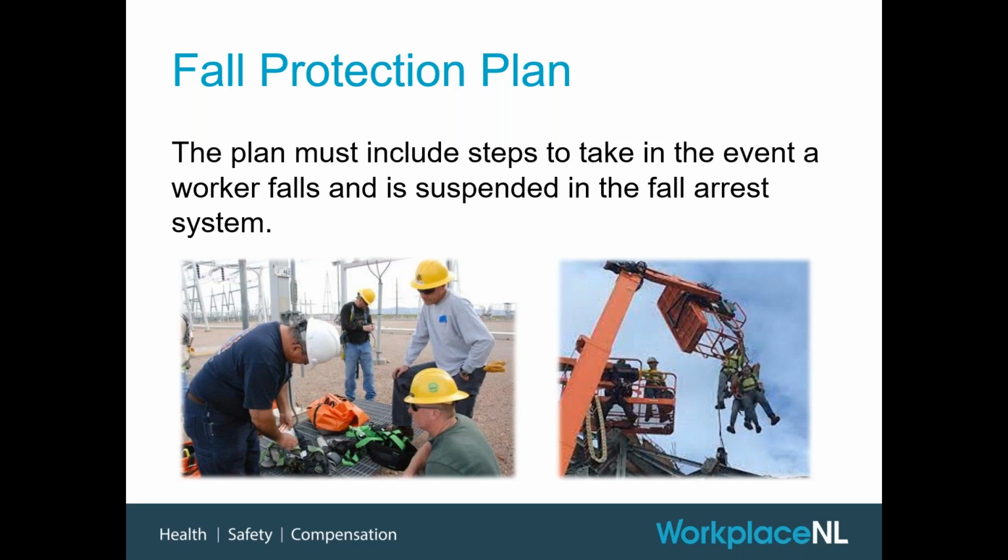The driver of that lift should be prepared. It's no good to have that second lift half a kilometer across your work area, or to have the driver gone to lunch, or maybe there's no fuel in that lift, or you don't know where the key is. All these things need to be ready to roll at the moment somebody falls. Again, the time is very critical for these suspension related injuries. And there are other options for rescue. You might use rope access if you've got people who are trained to do that type of work. There are different things you can do, but it's important that the plan is ready to roll.